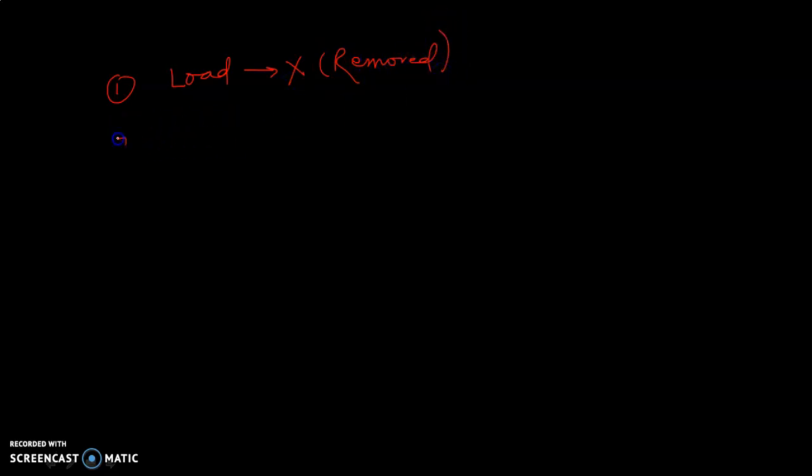And the second point, while applying Norton's theorem, coming under the procedure, is to short circuit the load terminal AB. This was present across node A and B, terminals A and B.